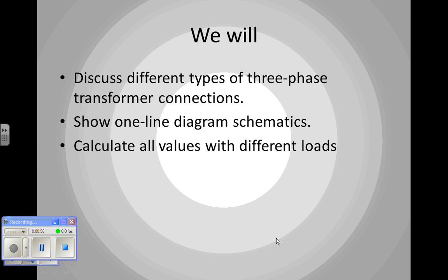and a single-phase load, because in an office, let's say you have a manufacturing plant, and you started out with just machine shops, and you didn't have any office at all, and you're doing your office stuff at home, and suddenly you realize that you're so big now that you can afford to have an office. So you add an office, and you realize, oh darn, I have nothing but three-phase power here, and I don't have 120 in place. So if I center tap this delta, I can get 120 on two phases, but that's really all on one of the three phases. So we're going to talk about that, if I can remember to, that is.